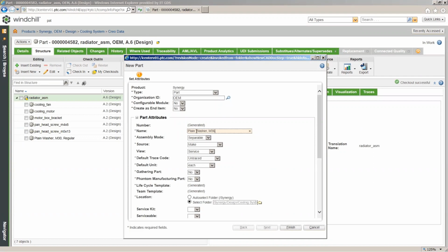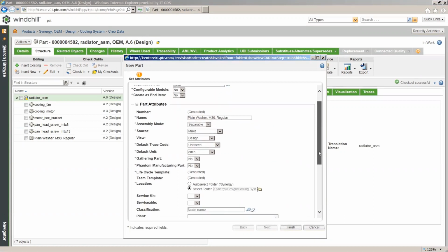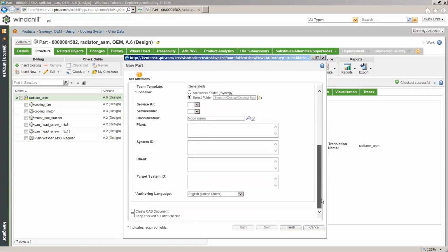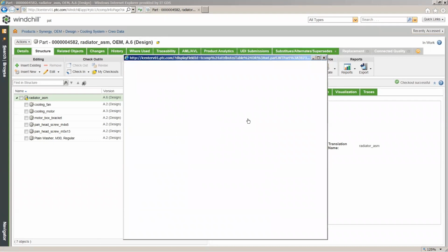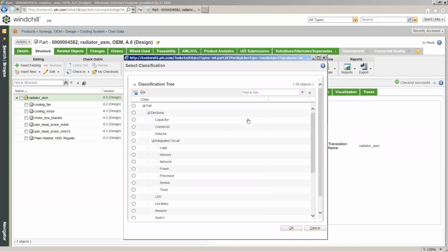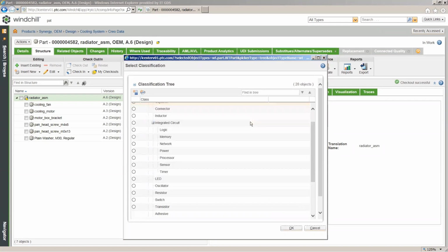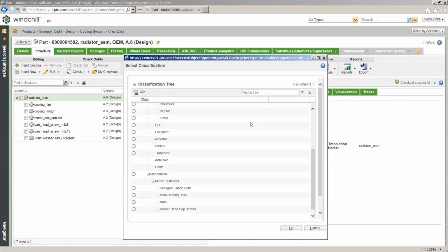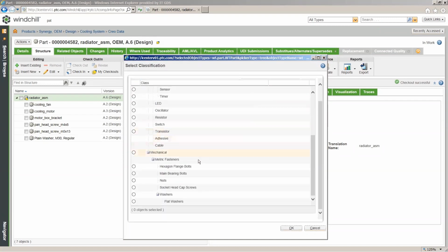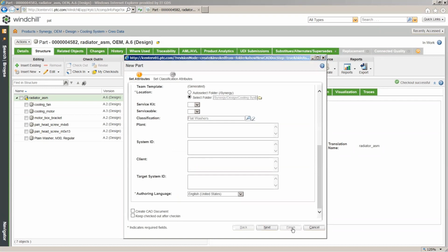If we're using this tool, you're not going to get any benefit from it if you're not using it the way that it's intended. So if this is a pain point for you, going in and searching for information, and maybe you have a lot of duplicate parts, then come in here and require a classification to be entered whenever someone creates a new part or creates a new document. They're not going to be able to add this object to Windchill without classifying it. So that's going to make sure that everything is easily searchable and that you're following a standard process.